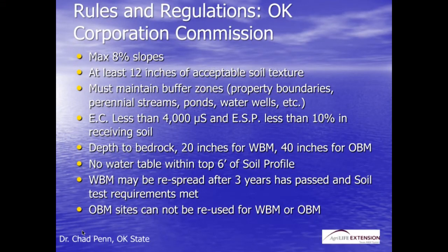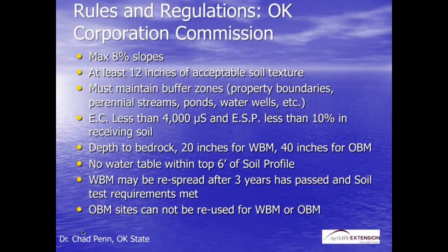Depth to bedrock, 20 inches for water-based material, 40 inches if it's oil-based material. No water table within the top 6 feet of the soil profile. Water-based materials can be respread after 3 years has passed and the soil test requirements are met. In Texas, it's a one-time operation, or it's considered a landfill as compared to our farming operation. The oil-based materials sites cannot be reused for either the water-based or the oil-based materials.